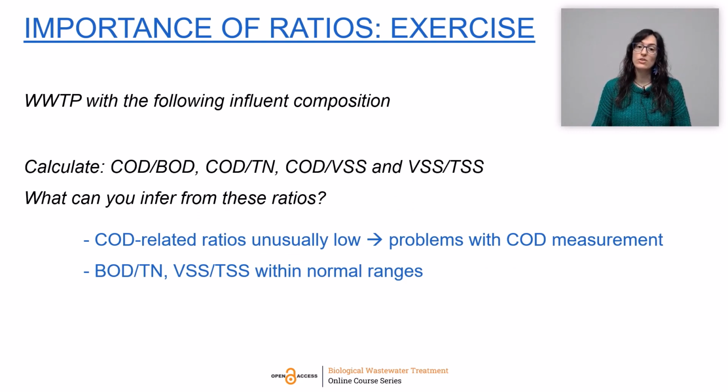So, after taking a look at all the ratios together, we can clearly see that those related to COD are always extremely low, and as mentioned before, we even have a COD to BOD ratio below 1. And all of this clearly indicates that there must be something wrong with the COD measurement.